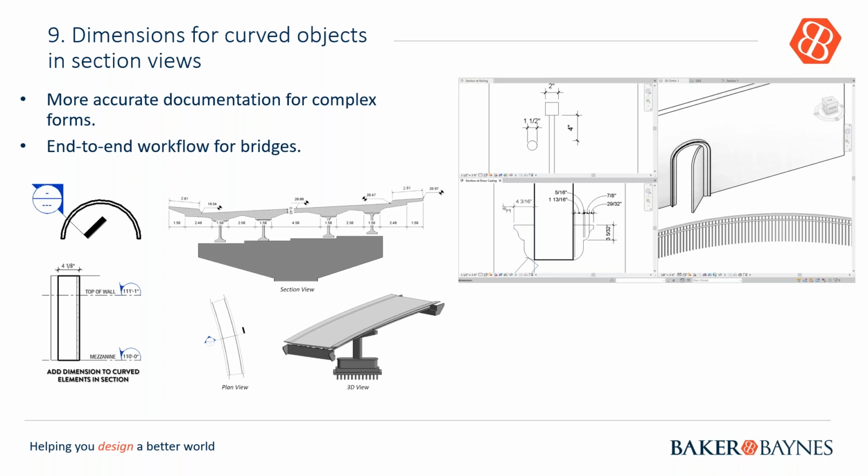In the previous versions of Revit, cutting through a curved element was quite awkward, right? You couldn't use dimensions on the elements, and it forced users to draw 2D lines over the curved elements, which, in terms of the BIM way of thinking, is not ideal. We want to get away from drawing 2D lines because we would like everything to be connected. In Revit 2019, you can now use dimensions on any cut curved object. You can see here what you would do: in plan view, you can do a cut and dimension it at that angle, right?